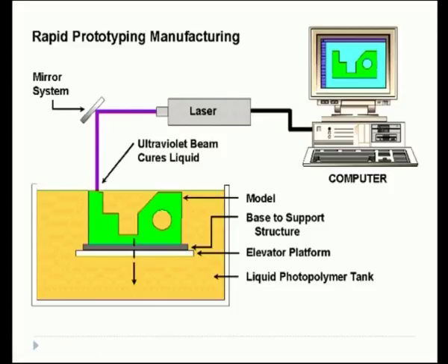Once the polymer has been kept in the tank and the related input has been given, the monomer is converted into polymer, that is, the process of polymerization is done with the help of UV light. Here we mostly use UV lasers, because different lasers have their own advantages and disadvantages. Sometimes we cannot use a particular laser for a particular type of polymer conversion, because here we are not using it for the purpose of heating the material.